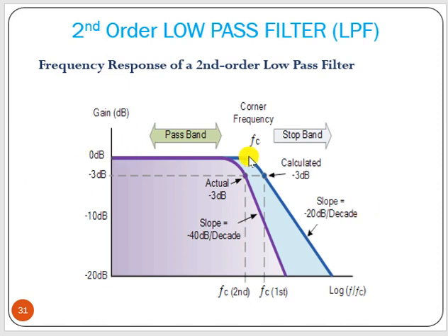That is the point you have to remember. Now here you have this low pass filter. This is your first order filter. Attenuation is minus 20 dB, but for second order filter, its attenuation is minus 40 dB per decade. Okay, and we can see there is a little shift of FC value.